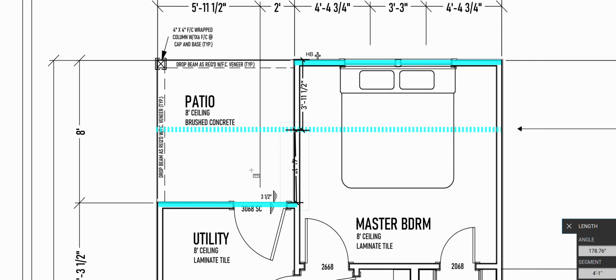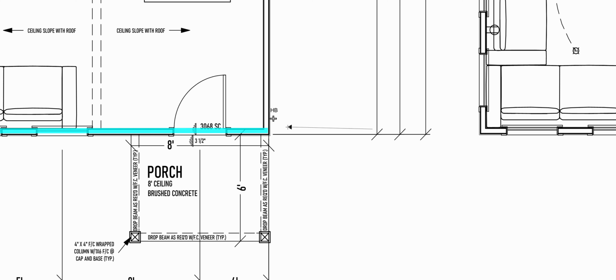So in terms of the left-right direction, from the wind blowing from the right or from the left, I've got a braced wall line A up top here, and I've got a braced wall line B at the bottom here. Okay, now the first question I'm going to ask myself is, I'm designing by wind, so the maximum I could go is 60 feet. I got 54 feet here, so I'm okay.